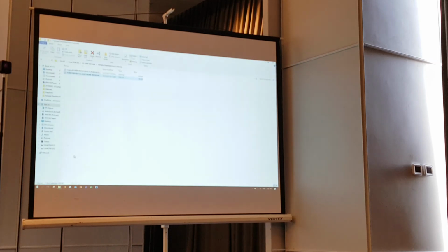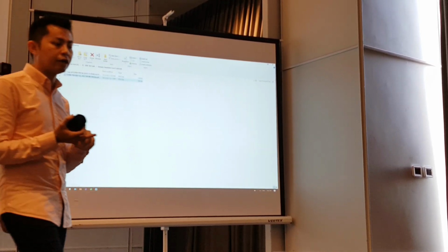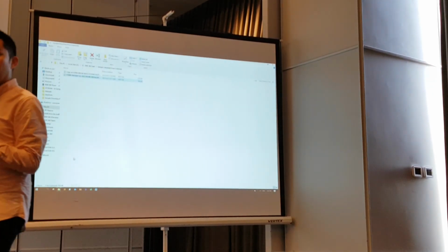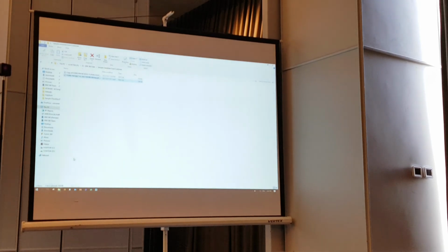Alright, so once you guys are done that, your PXML file, if you don't have the software to open up the PXML file, you can use the notepad to open that one up. Once you open that one up, you should be able to see the whole list is there. What is the rebar size, what is the total length, where is the cutting point, what is the total weight, and so on.